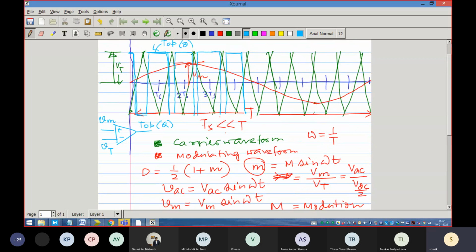You will see that the pulses narrow considerably in this zone. Here the pulse is considerably narrowing, which is not at all surprising. In the negative zone the pulses will be narrow. Don't say the duty ratio is negative.